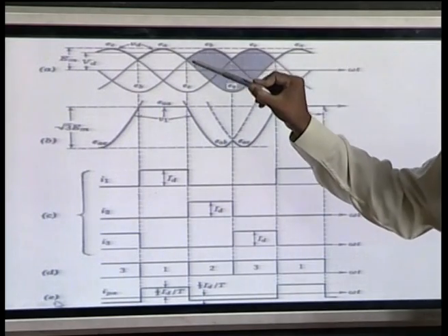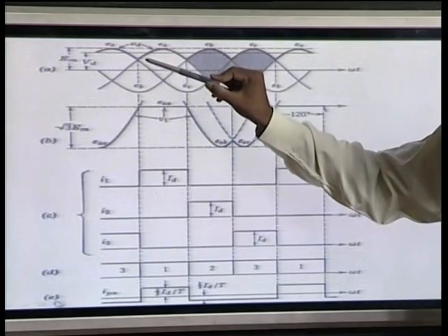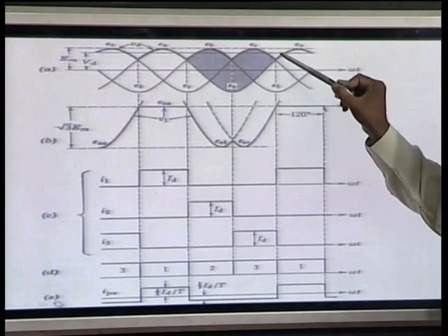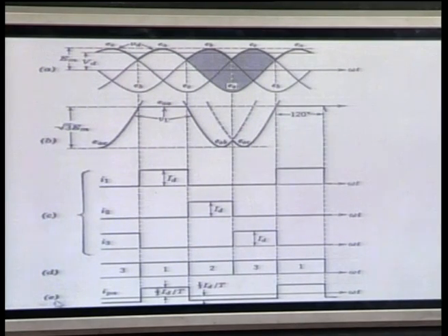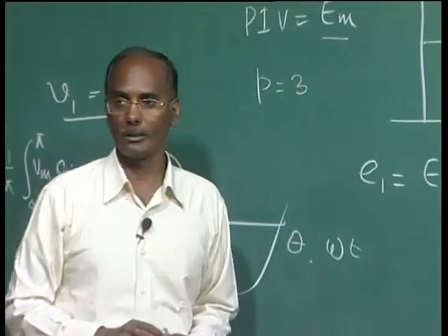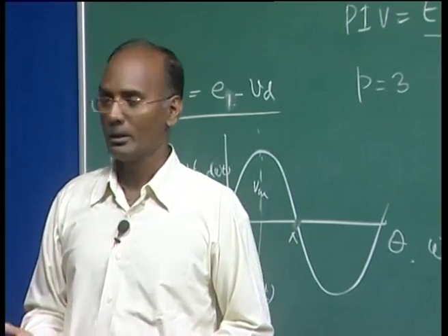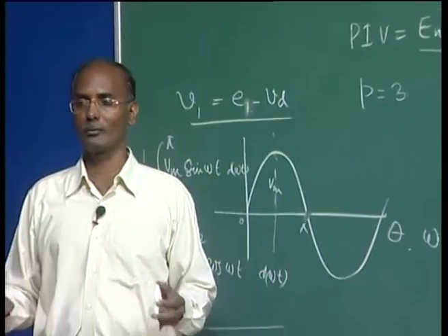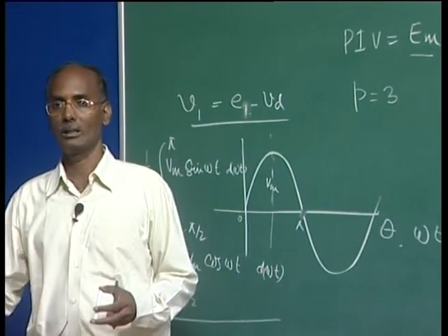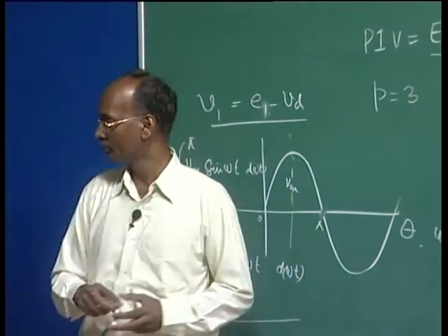And you see that in one cycle there are 3 pulses. So, we are getting a 3 pulse cycle. Now your pulse number P is equal to 3 in one cycle. So, it is a 3 pulse 3 phase rectifier circuit, and it is simply called a one way circuit, 3 phase one way, because the current always flows one way and does not flow through the other two.